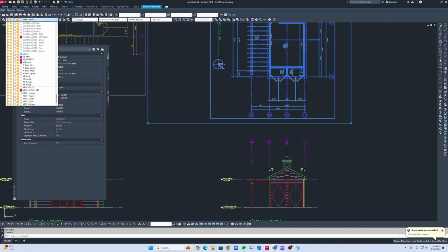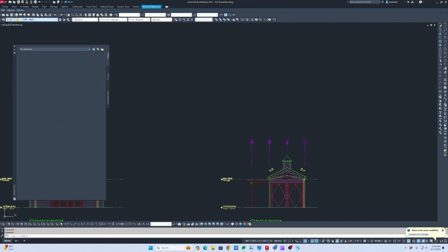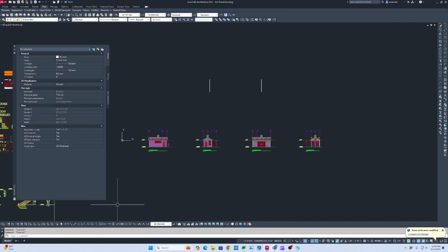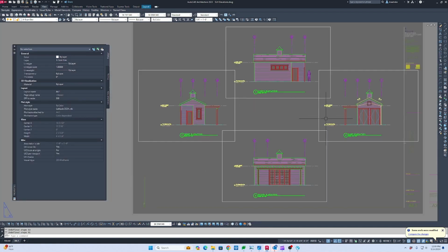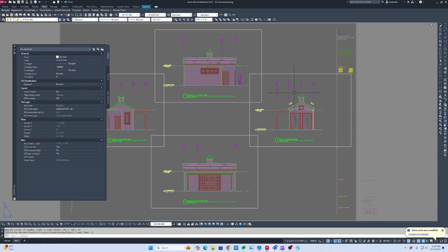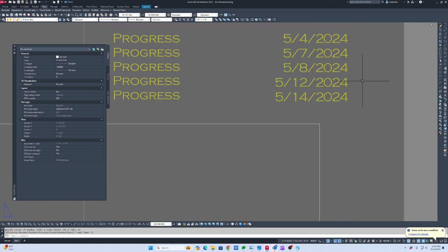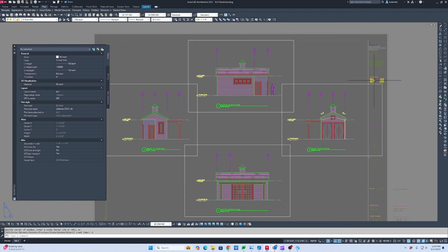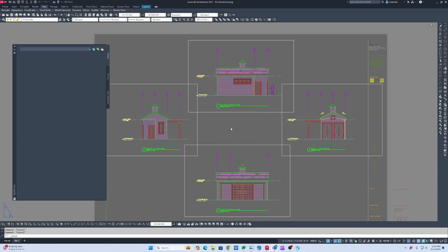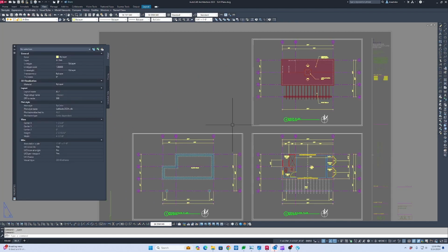Turn our XREF back off, just freeze it. By turning the XREF off, switching to paper space goes much faster. So this sky update, that is updated. Okay. So let's do another progress print and call this a wrap. So just save that just in case.